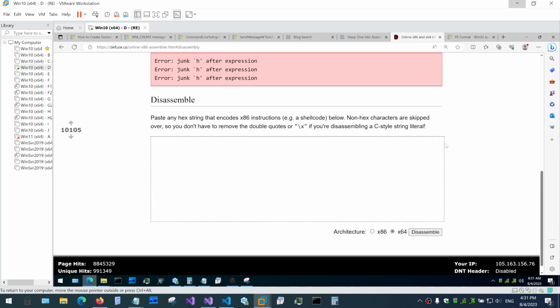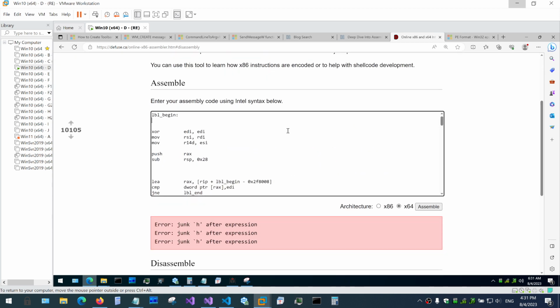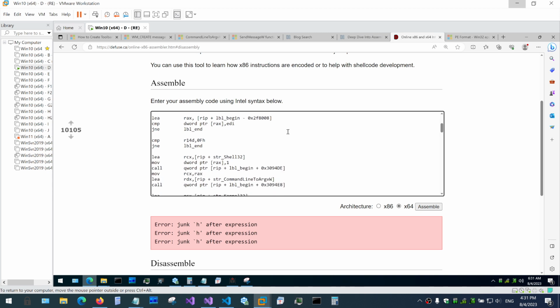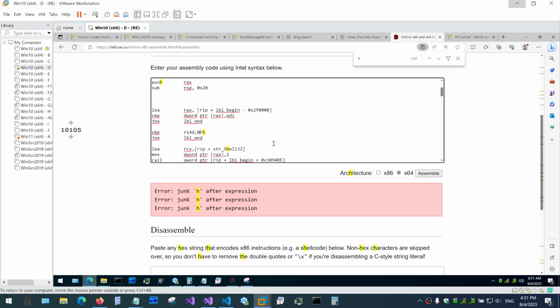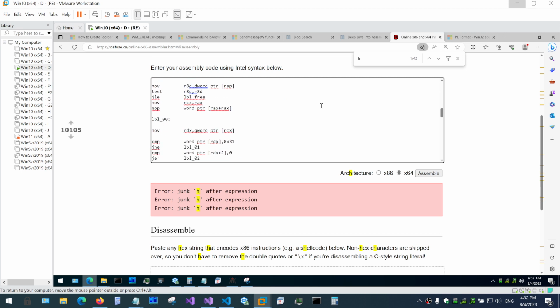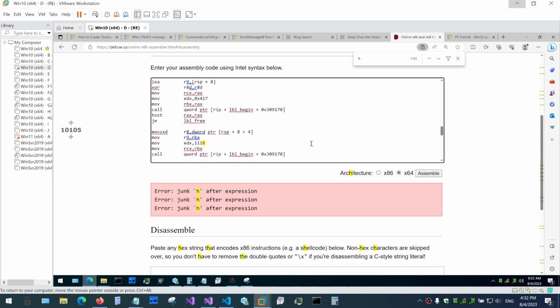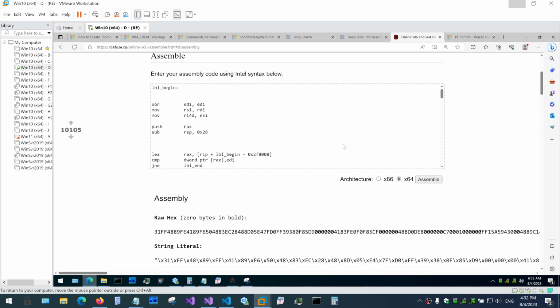Okay, let me try again. Okay, it didn't like H, and I believe, yeah, unfortunately Visual Studio puts these H's instead of hex numbers like 0x, for instance over here, it's 0xf. I just have to remove them and then copy and paste it into Notepad, also over here, in case I have to modify something again. And this guy also needs to be replaced with this. It's a weird quirk of this assembler, and let's do it. Okay, here you go, it worked.